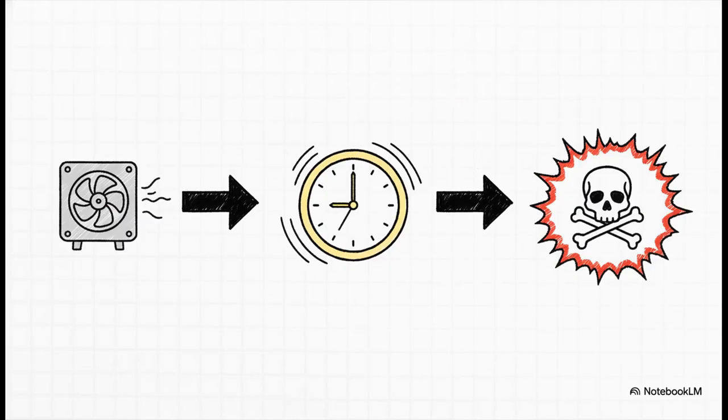It's a straight-up cause and effect relationship. A weak bathroom fan means a longer fog time on your mirror. In the industrial world, a weak mechanical ventilation system means a longer persistence time. And a longer persistence time directly extends your hazardous window. If the gas lingers longer, your area classification absolutely has to become more severe to reflect that extended danger.